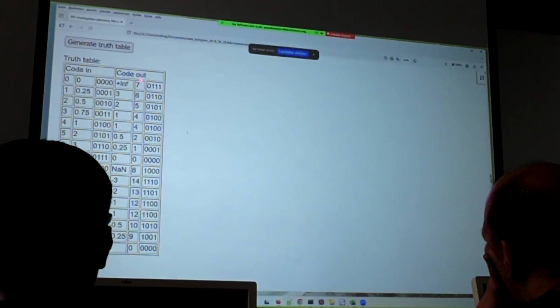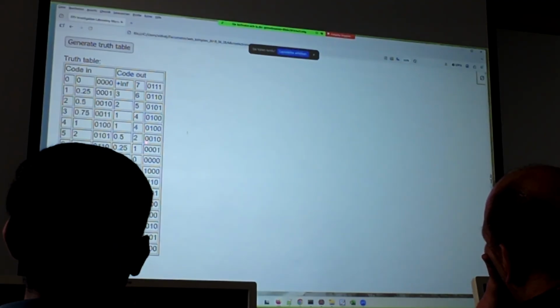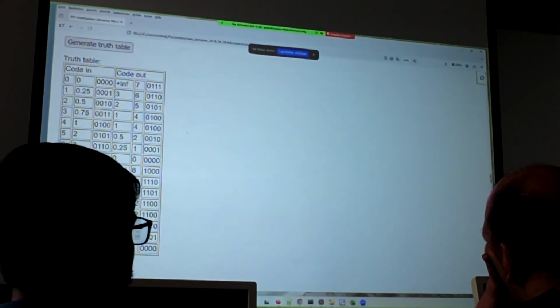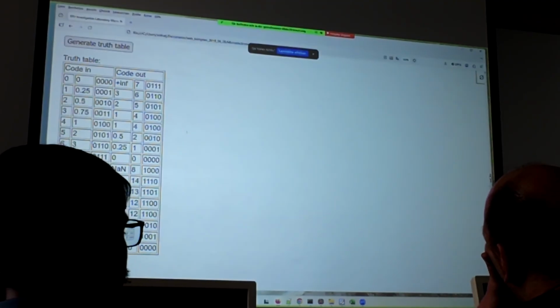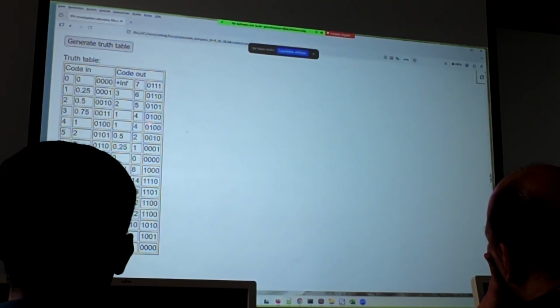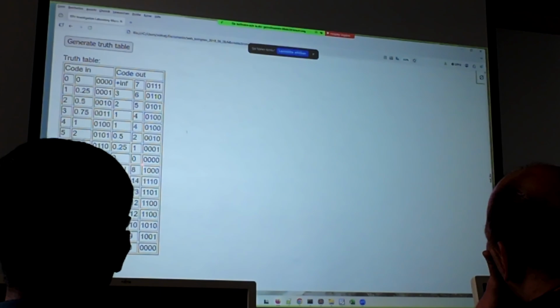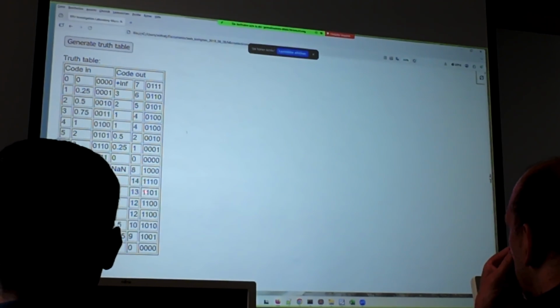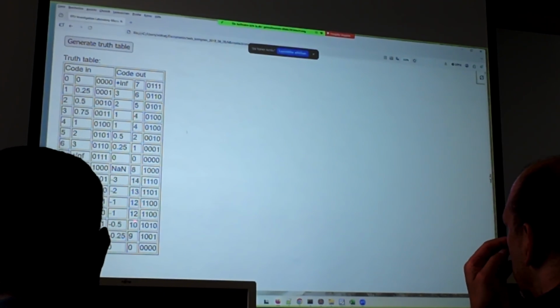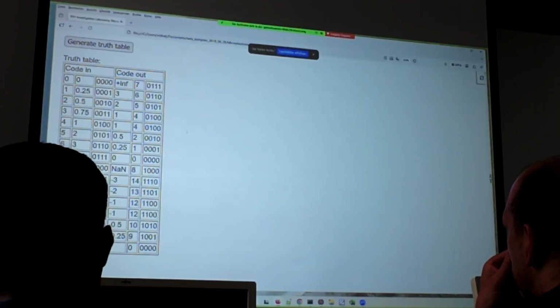Then we can go in there and say, okay, for one column here, the output 3, I have to combine this with our lookup tables and our multiplexer, so I get these hex numbers. So I start here with 0, the 4 zeros. Again, the second one is also 0, then I have 1, 1, 1, 1, so it's an F, and then I have 1, 1, 1, 0.